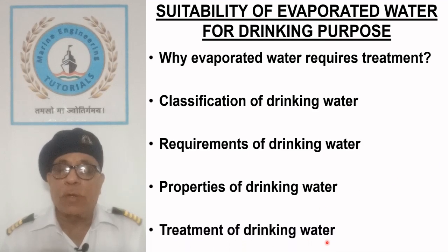Treatment of drinking water. Although freshwater generator produces water of high purity, it tastes flat as it does not contain any dissolved solids and has very little dissolved air which has been removed during the distillation process. To make evaporated water suitable for drinking purpose, it requires mineralization and sterilization.